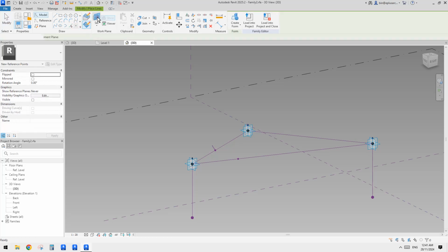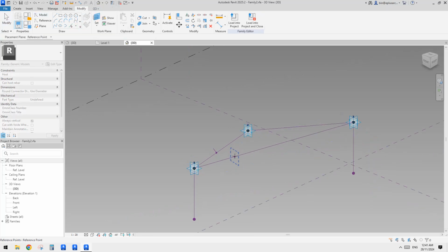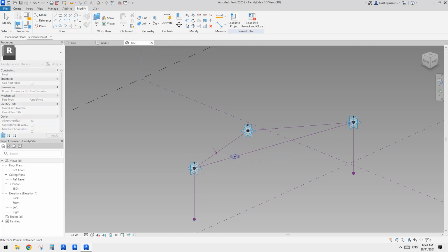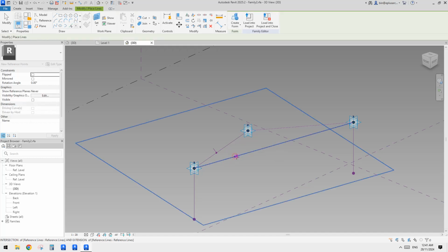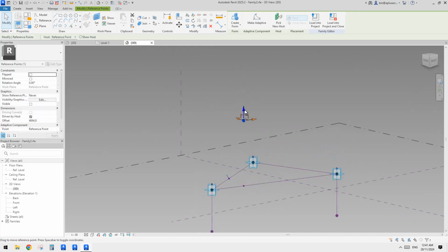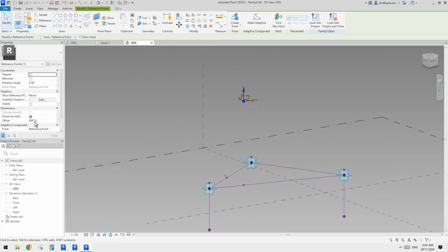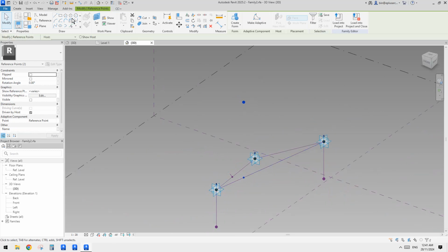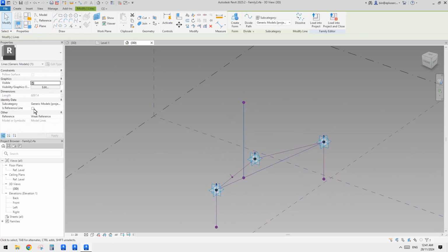So I found an easier way of doing this. You can just place a point, use draw on world plane, set world plane, pick the horizontal world plane on this point, and then finish OK, and select this point, and drag it up just high enough, roughly here. So yeah, 6 meters should be enough, right? And then connect these two to create a reference line.